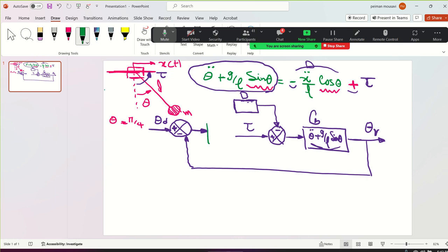I'm just joking. So you are comparing the desirable input with the real output. It sends you the error signal. We're going to go to the math shortly, in the next two classes. Based on this, you're going to design, and this is the whole course about this part, the controller, like a lead-lag controller or a PID controller. I'm going to teach you eventually. And this sends you the signal to keep the angle of the leg at 45 degrees.